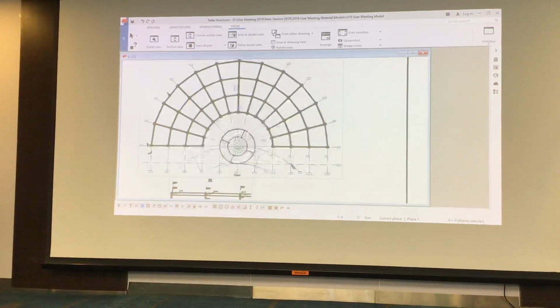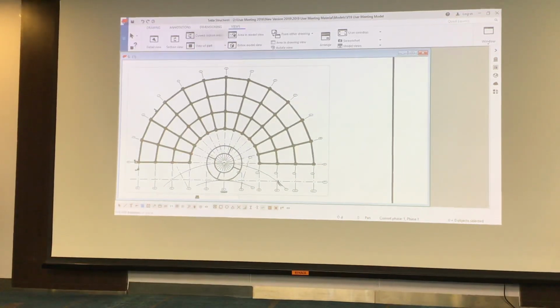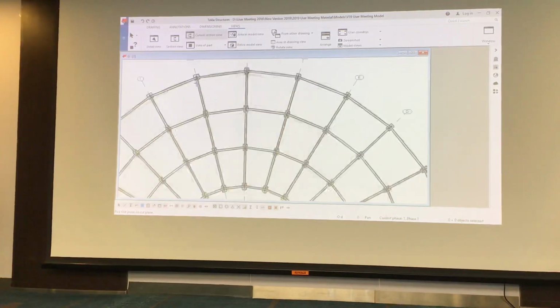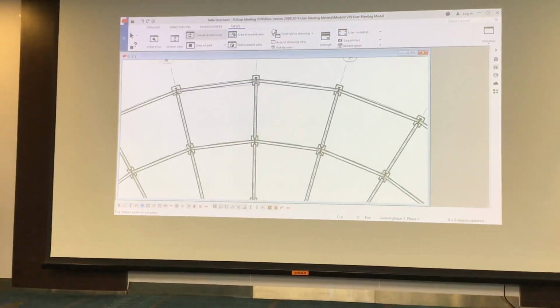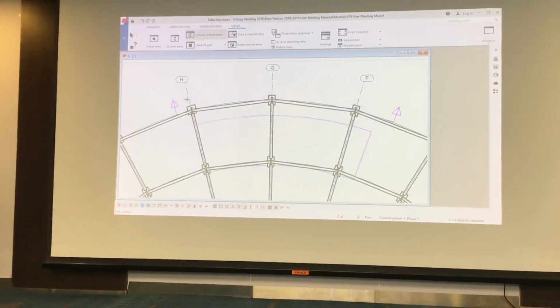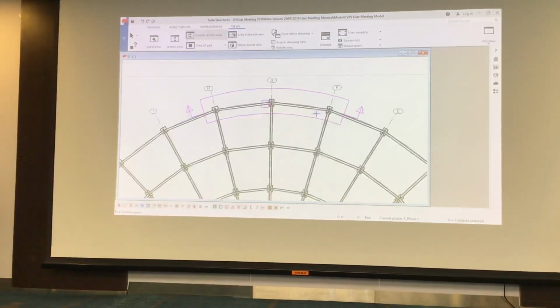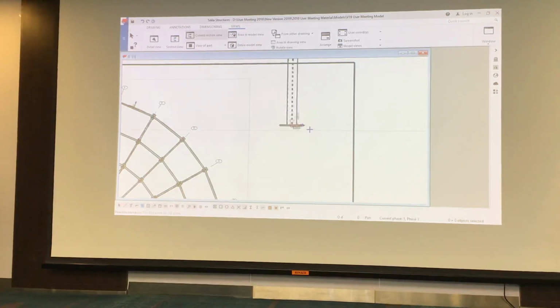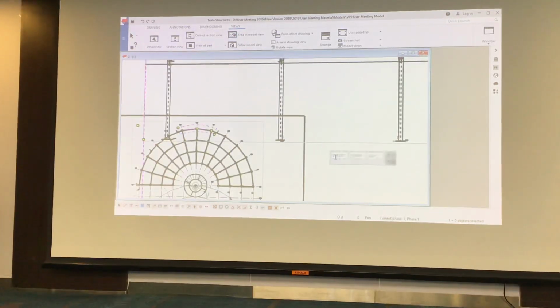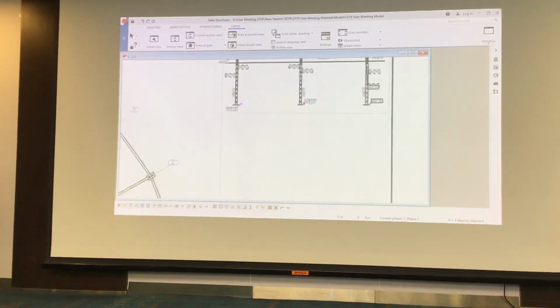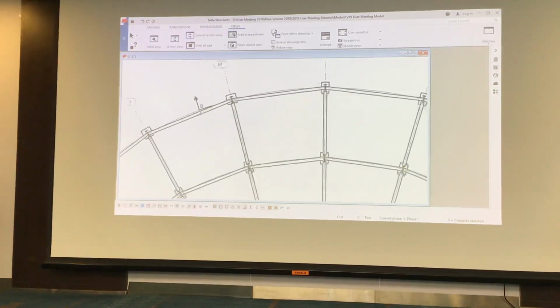There we are. So again, let me show you that layout again. So you say I want to create a set. I want a view looking on here. So you say I want to view from this point to this point to this point. I want a view looking on there like so, and I want to drop it at that point there. Okay, click on that. Mini toolbar, scale 1 to 150. Use that mini toolbar, is great. Look, you've got a view looking on there, as you can see laid out like that.